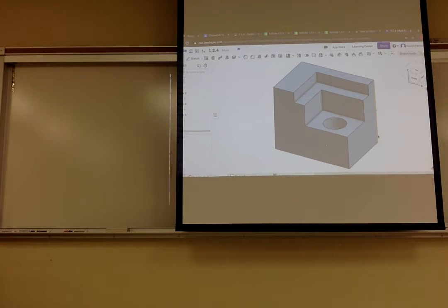What shape are you wanting to extrude? Whatever you want to remove, you need to make the outline, make a sketch of it. Then you click extrude, and instead of adding, like normal, there's an option for remove. It always assumes extrudes are adding, and typically they are. But you would just go to remove. Instead of adding material in that shape, it's going to remove material. So that's how you do it. In order to do that, you need to draw what shape you want to remove.